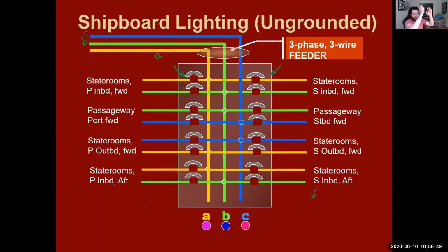Okay. So the lighting panel for the whole starboard side of the ship. That's not it. You go to the port side of the ship. If that wasn't it, then you go into the engine room lighting panel. And then you go into machinery, and you just keep slowly going through until you narrow it down from the entire ship has a ground on A to, oh, it's only on the AMS lighting panel. Now, where in AMS is it? And then you can actually get it down to just maybe a small stateroom that you have to check instead of a whole ship anymore.